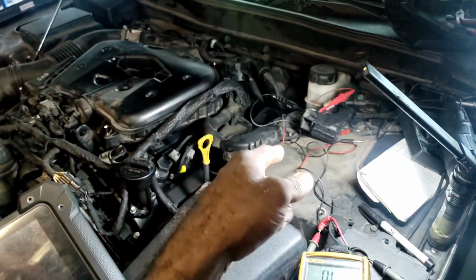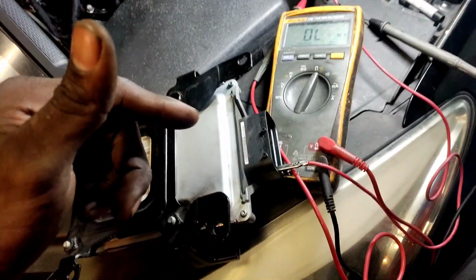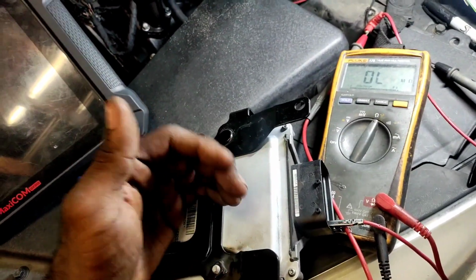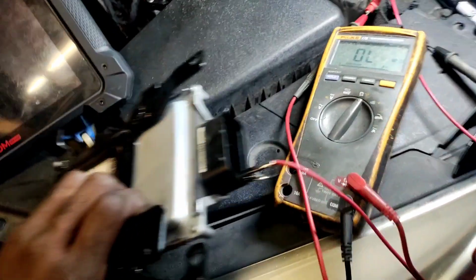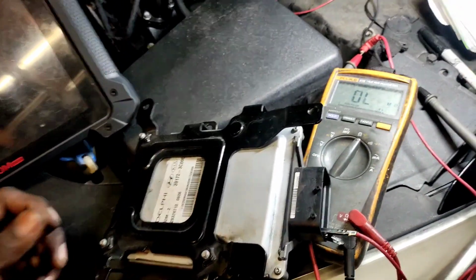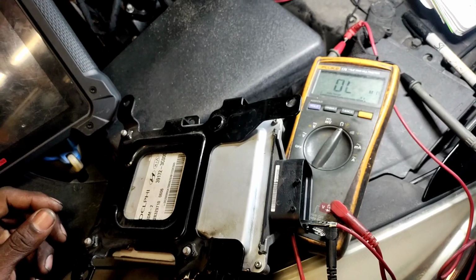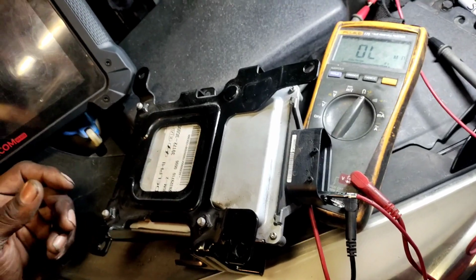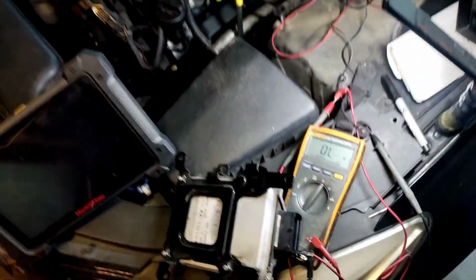So like I said, I checked resistance at the wiring going to the injectors. They were fine. Let me show you what I found out with this one, while I'm concluding that the issue I got is just pretty much a bad section on the pin. So we just didn't have any continuity. And I guess once the amp ramped up, having a load to activate that injector, it just probably had a bad spot. And then you got the vibration of the engine and the harness. And I guess that's why I'm hitting that dead spot for maybe a millisecond, and it generated a light, went to a limp home mode. So let me show you what I found out.